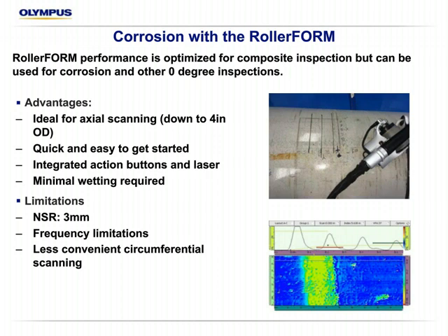It's very quick and easy to get started. On a very smooth surface, it doesn't take much wettability. If you do have a very rough surface, it might take a little bit more water. But basically the coupling is done just by putting couplant on top of the material, and it goes through the water, through the membrane, into the surface. But it does have a limitation. The near surface resolution is not as good as any of the others.